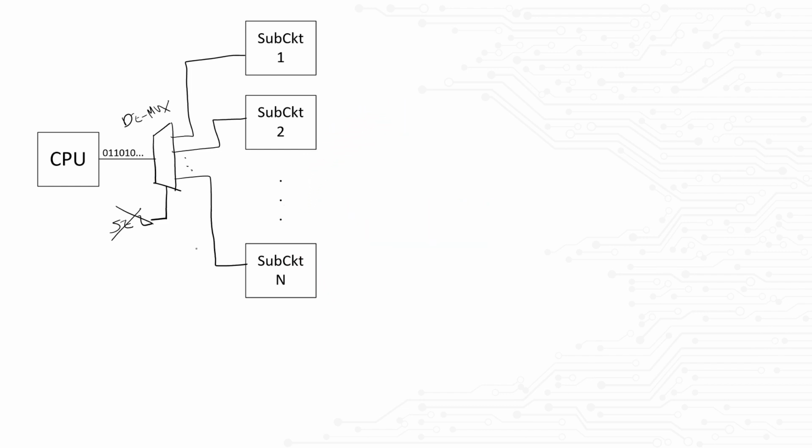Well, if the interviewer gave us a clue that a mux-like structure is what we needed, then we need to figure out how to control the mux without dedicated select bits. As a digital designer, you might have already figured it out. But if you haven't, that is okay. That's why we're here. You can tell the interviewer the following.